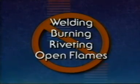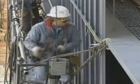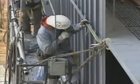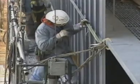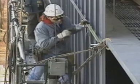Welding, burning, riveting, or open flame work should never be performed on a scaffold suspended by fiber or synthetic ropes. Treated or protected fiber or synthetic ropes should always be used if the work will involve the use of corrosive substances or chemicals. As is true of other types of scaffolds, suspended scaffolds should not be moved until all unattached materials and tools have been cleared from the platform and all workers have dismounted.